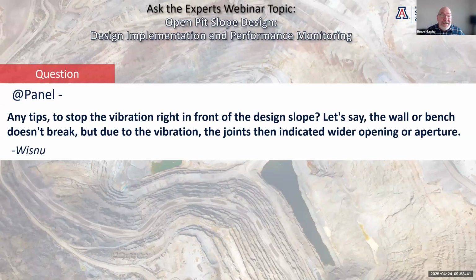I think the production guys now are pushing: let's blast big blocks, we do it with electronic detonators, we're keeping the energy down. Well, let's make sure we chart what they're doing and check what they're doing, and make sure we're not lifting the trim or having a good go at lifting the slope in terms of instability in that damage zone. Anyway, sorry for the diatribe.